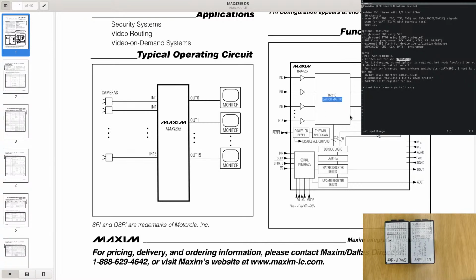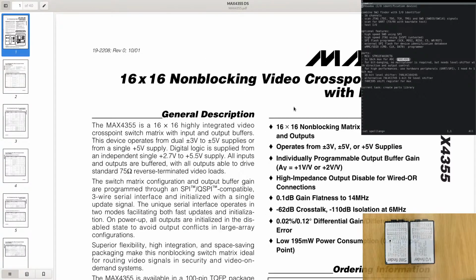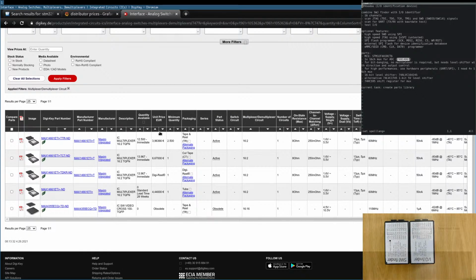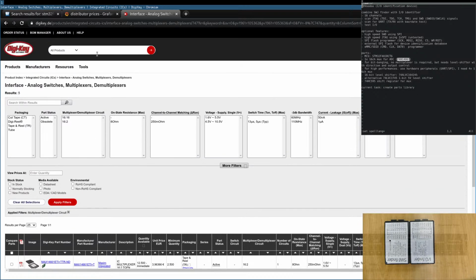Here, switch matrix. This is what I kind of want. I want a switch matrix to decide what goes in one way and what goes the other way in the analog domain, not in the digital domain. And if it's in the digital domain, I want it to be bidirectional and compatible between 1.8 volt to 5 volts. This doesn't do it. And I didn't find a switching matrix which was able to do that. Analog matrix. Does this? I found something very similar though.